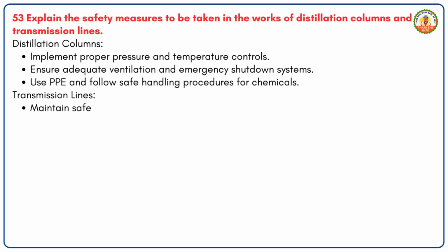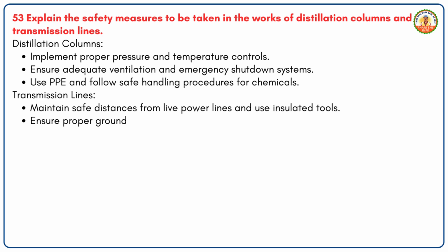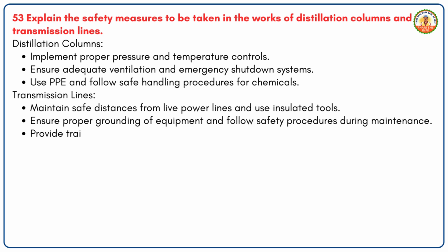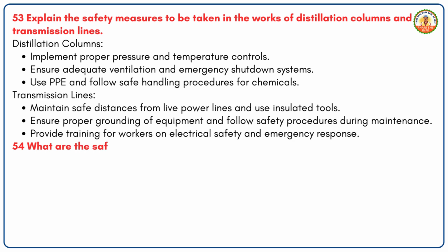Transmission lines. Maintain safe distances from live power lines and use insulated tools. Ensure proper grounding of equipment and follow safety procedures during maintenance. Provide training for workers on electrical safety and emergency response.